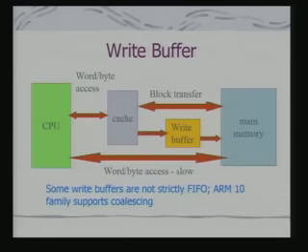Now, obviously, the issue that comes up in this context is that the data in the main memory and the data in the write buffer are not consistent. Why? The data might have changed, and that data is written into the write buffer, and the data in the main memory is not yet updated. So, that is an important concern when you are programming the system.